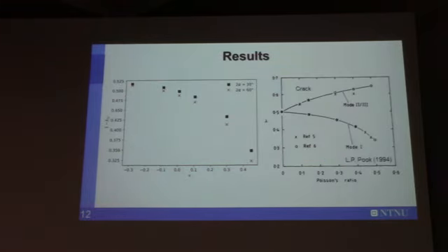What's important for us was to identify the strength of the corner point singularity. But to do this, we have problems with the stress field at the free surface, because we have numerical instabilities. You have to extrapolate the values from the integration points to the nodes.